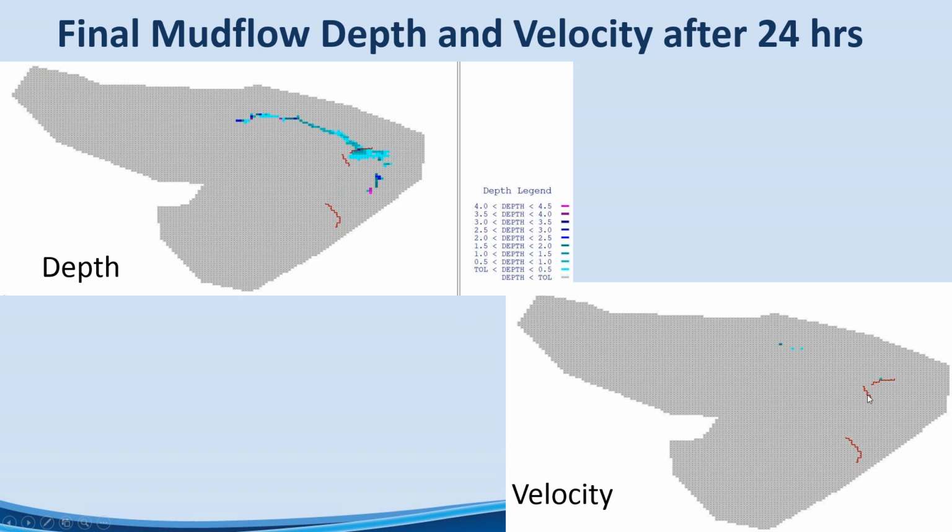And this is not moving at all inside the tailings dam. There's a little bit of mud flow seeping or oozing along downstream here, just barely, but after 24 hours, all of this would be essentially deposit. Now, are you going to get exactly 3 feet or 3 meters of deposit here? Probably not. But the idea is that you're going to get something that's representative of the area of inundation for the viscous stuff up here and for the fluidized stuff down here.